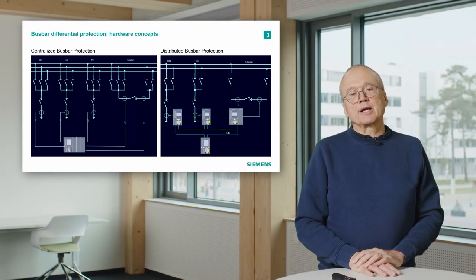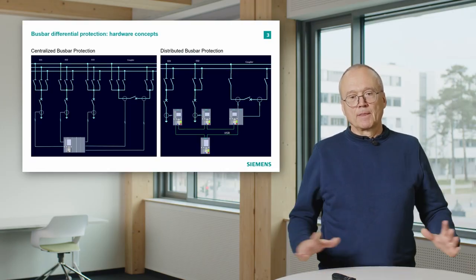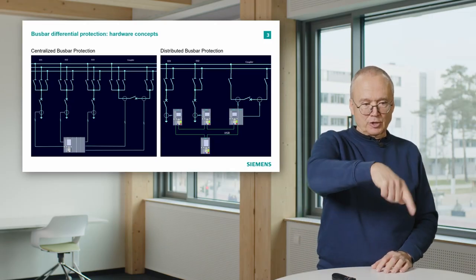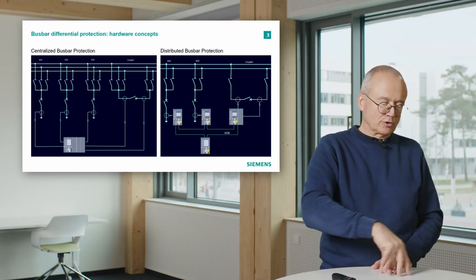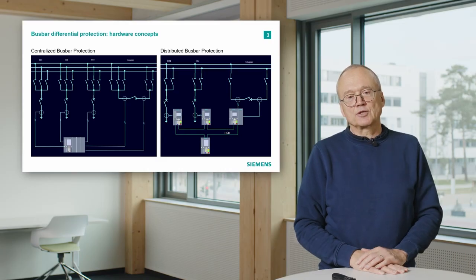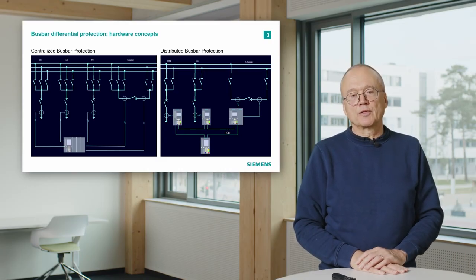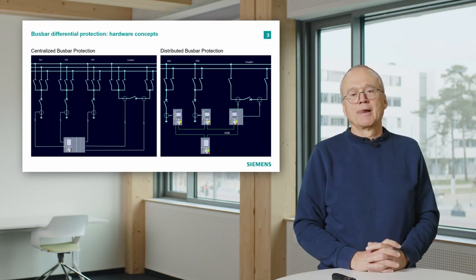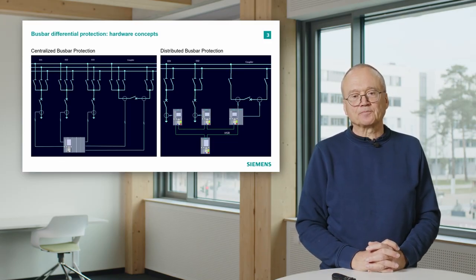In the previous generation, we had a star connected thing. That means we had point-to-point connection from the central unit to all feeder units. With CProtect 5, we have now this ring-type communication available because we make use of modern process bus technology.